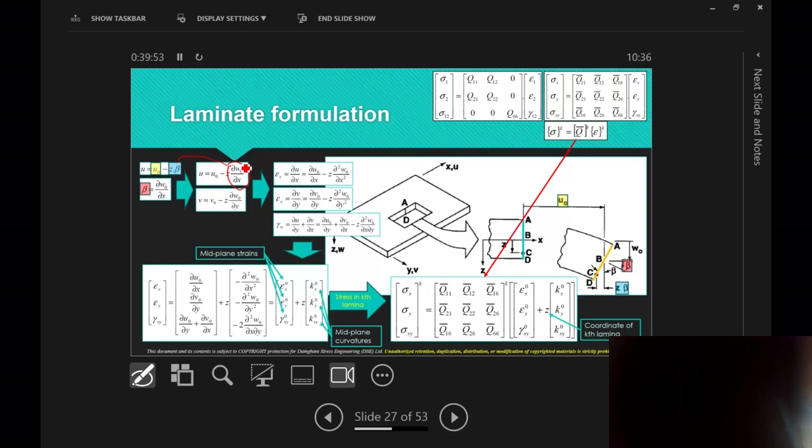The same could be said of here. And epsilon, mathematically, these are the things they haven't told you, very possibly, is that mathematically the way epsilon is explained or denoted is that differential of deflection with respect to the x-axis. That gives you epsilon x. So you just plug in all the values. So you've got the u is here. So if you put the u in here and differentiate that, essentially this is what you get.